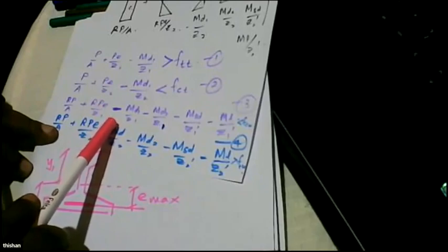Then we'll have a bigger I value and different Z values. And then the whole bridge or the whole slab will participate in resisting the superimposed dead loads, like the weight of the walkway, the weight of the asphalt concrete, the handrails. Those are minute, but whatever it is, it will be the composite action.